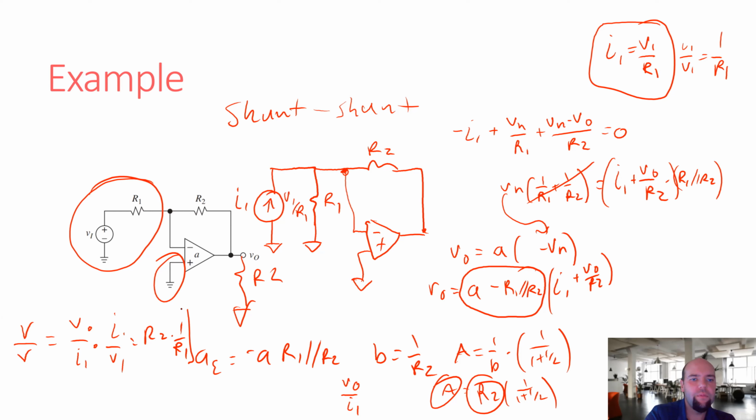That's the standard form, right? So V out over V in for this circuit, the overall gain, is going to be R2 over R1. Oh, it's negative, isn't it? Yeah, I left the negative out. Sorry, I made a common mistake. We can't leave it positive, it's got to be negative.